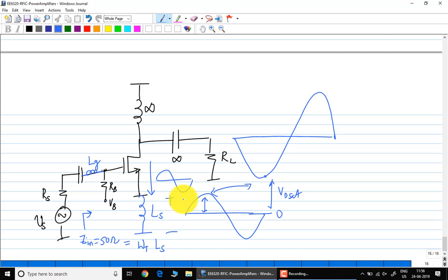Does noise ever come into the picture for the PA? Normally no, because the signal that you are putting out of the DAC is already several hundreds of millivolts. You are gaining that up further. The signal going out through the antenna is several volts. Okay, so noise is not a concern at all.